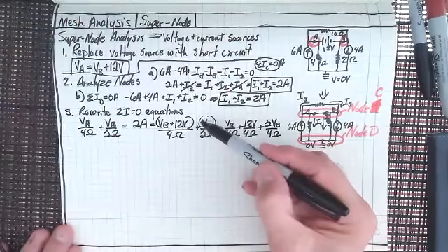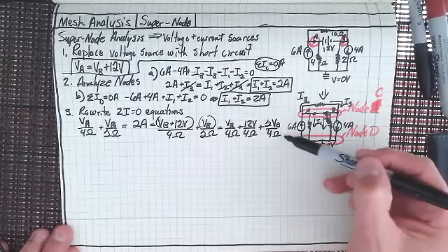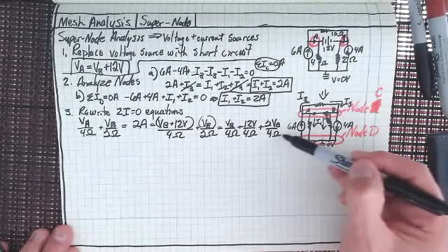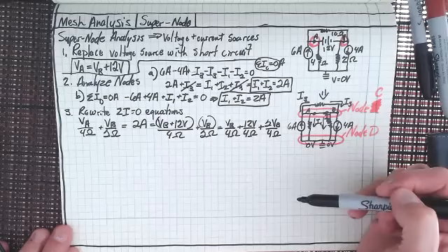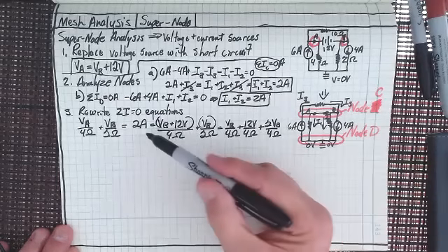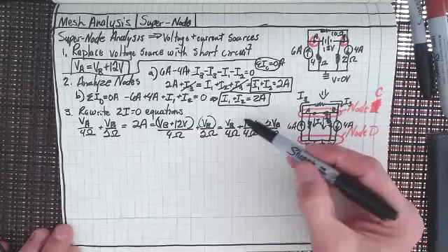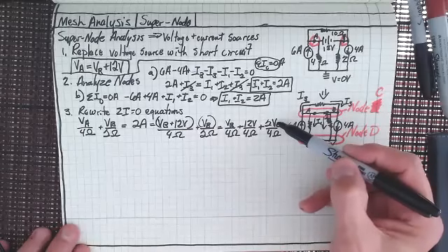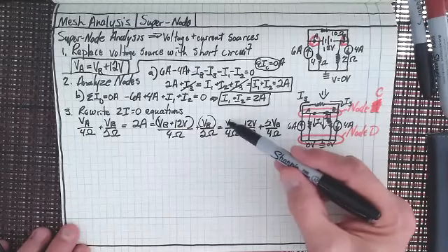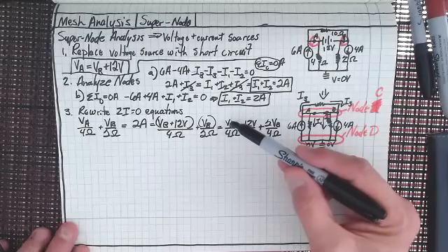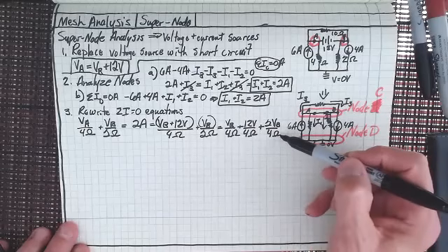Haven't we just multiplied the numerator by 2 and the denominator by 2 so that we can get common denominators here now? Right? And that equals 2 amps. So 2 V sub B plus V sub B gives me 3 V sub B over 4 ohms.